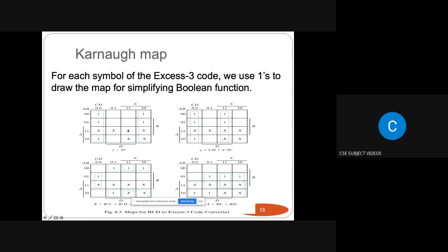So here in this Karnaugh map, we have to consider the minterms 10 to 15 as don't care. So we are representing the don't care condition as X here. If we want to include this don't care in our mapping, we can consider this don't care value as 1. Otherwise, it is considered as 0. Wherever it is necessary, we can include that. If not necessary, we don't bother about that. So it is only named as a don't care condition.